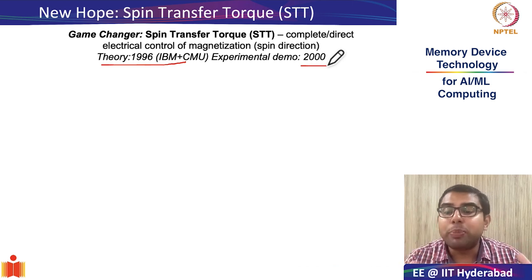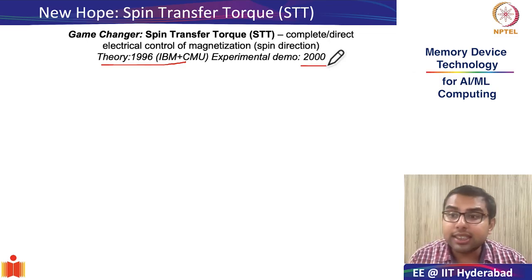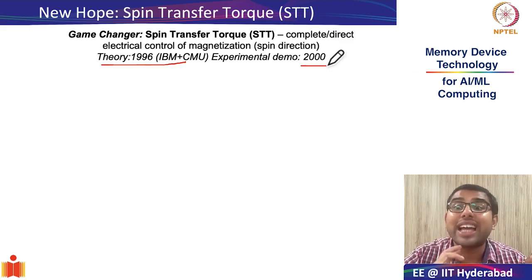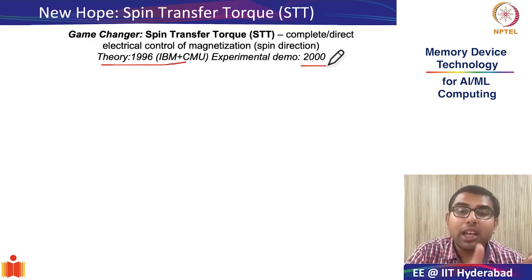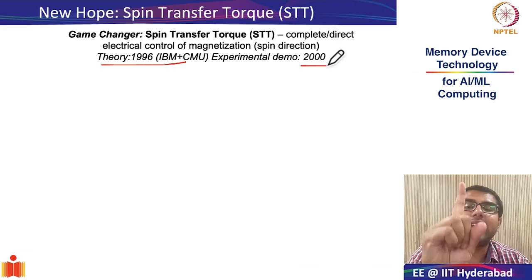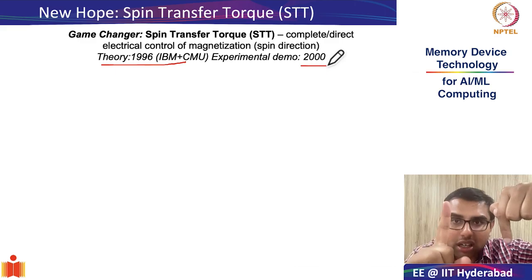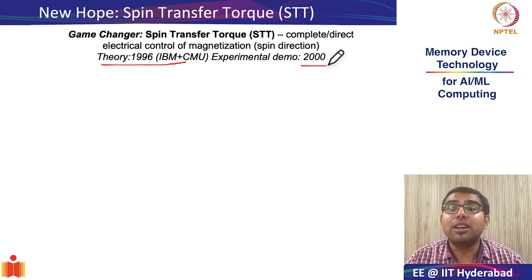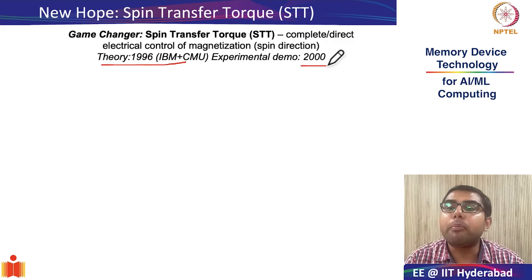So what does this spin polarized current, which has spin oriented in one direction, do? Upon entering a magnetic material, it can alter the magnetization of the magnetic material. Suppose the magnetic material has a polarization in the up direction. Imagine a lot of spin polarized current in the down direction enters this magnetic material. Because there is a spin angular momentum transfer from the electrons of the current, this can flip the magnetic moment of the material, causing it to change.